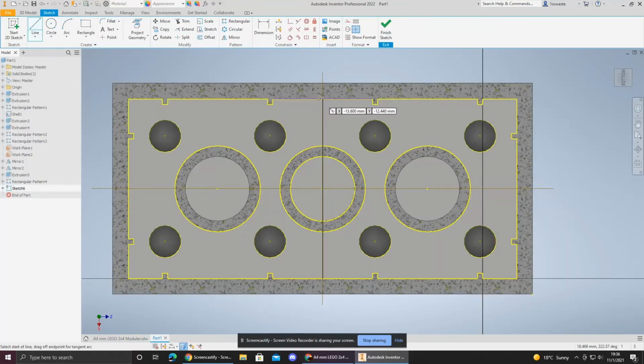We can now simply draw a line traveling 0.4 millimeters, and then a rectangle traveling from one side to the other, 0.8. Please note that this may not be the cleanest way to go about this. Using the dimension constraint between the line and another line is far cleaner.